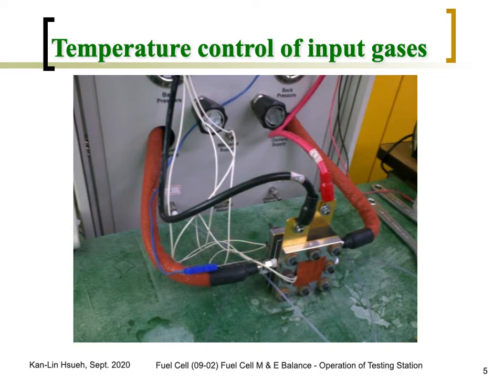So we added the heating tube over here, not only insulation but actually a heating tube, to heat up the inlet gas, because we found out that even when we bubble through the water tank, the temperature can reach about 80 degrees, but after going through the pipe with the insulation, when it goes into the fuel cell, the temperature may drop to 40 Celsius.